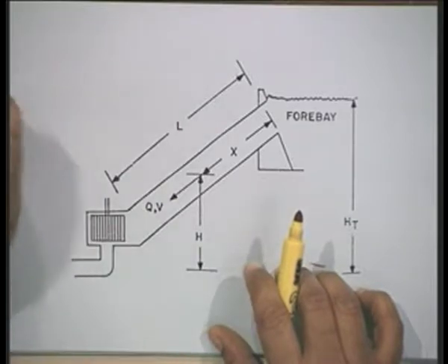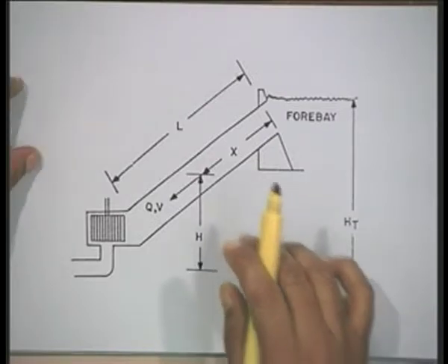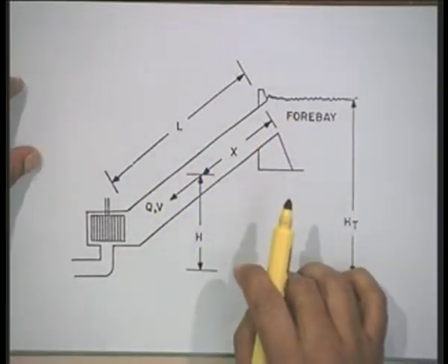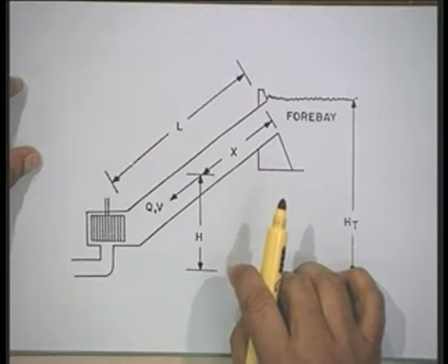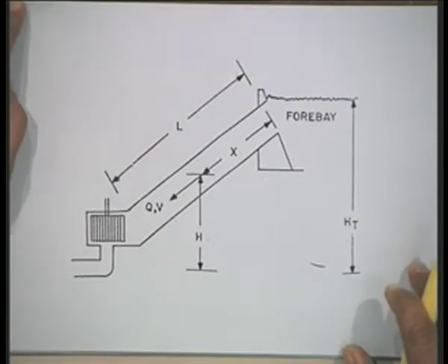The characteristic of the hydro turbine is determined by the dynamics of water flow in the penstock, and we shall determine the transfer function of the hydro turbine.